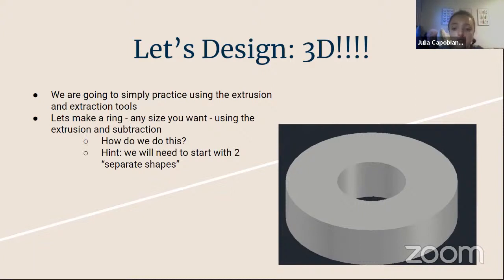So even though we were measuring everything correctly and we made the hole a certain radius, it didn't fit because we didn't take into account tolerance. So we had to reprint it. But that's just something to keep in mind: 3D printing is pretty accurate, but there are little variations in it that can change what you do.